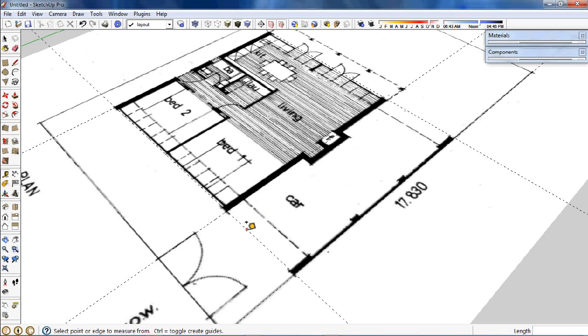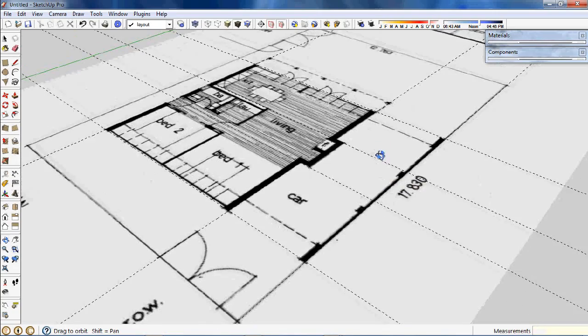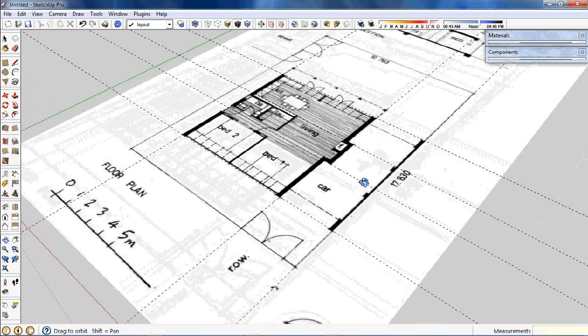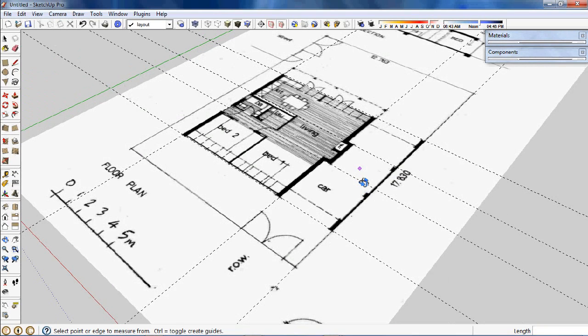Well, 3600, so typing 3600 is a brick module dimension, and I'll come back from the same construction line at the back there, doing the same sort of thing, hovering somewhere around about the 3 metres, and typing 3000 will give us another accurate brick dimension. So this building being laid out shouldn't need any brick cutting, which is a sustainability concept to try and minimise the amount of wastage on site.